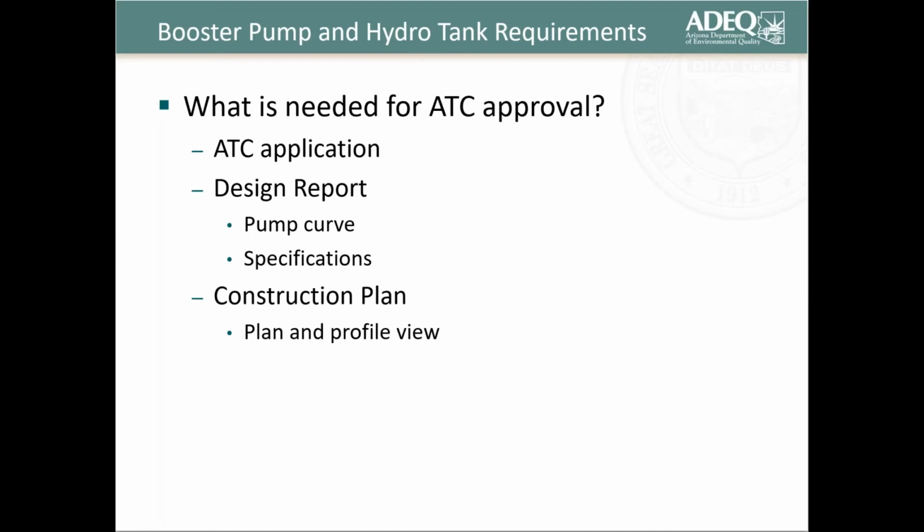And then usually they're missing specifications. So again, if you have those manufacturer manuals or anything related to what's being installed, include those in the design report. It helps the review process be a lot smoother and avoid those deficiency letters. And then missing that pump curve, as I had mentioned.